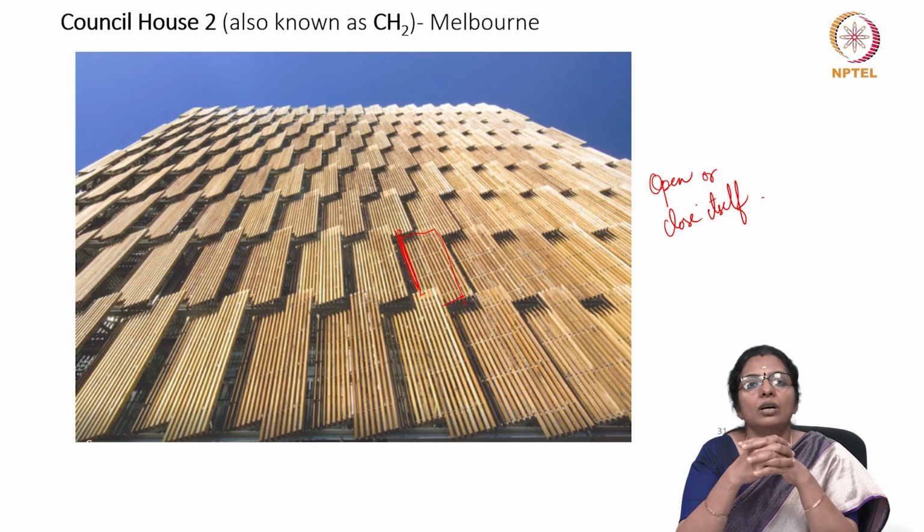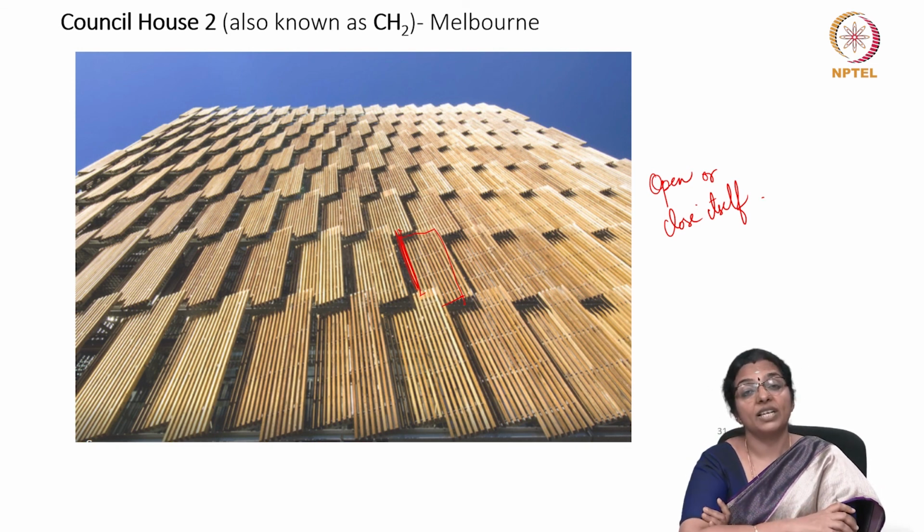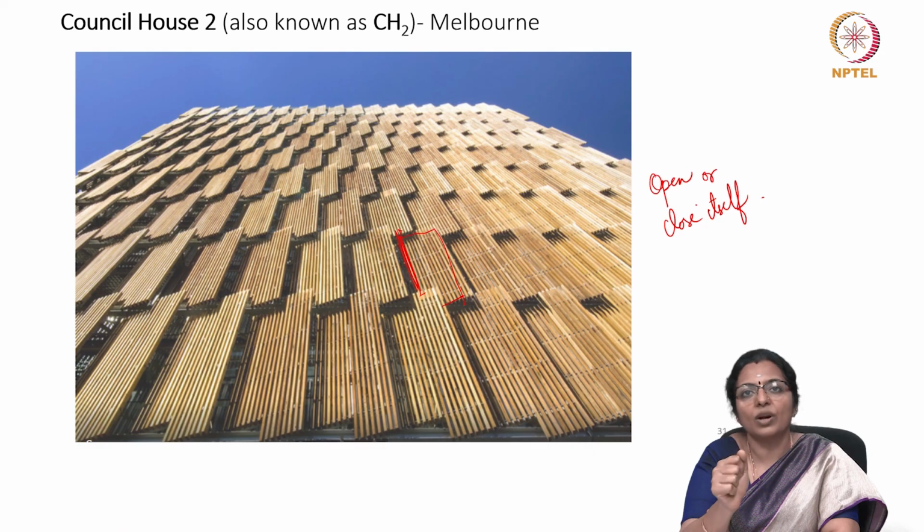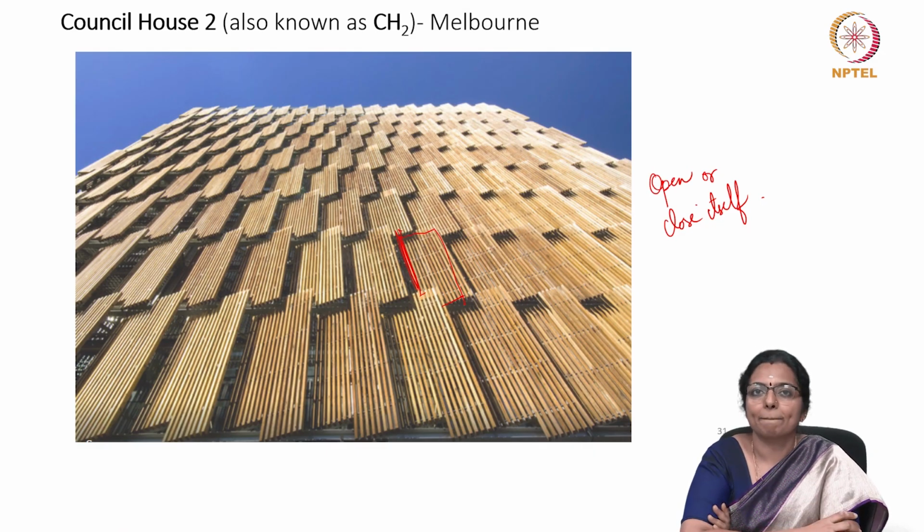And therefore, kinetic facades, even though their initial embodied energy may be slightly higher, will definitely in the long run be productive by having a reduced operational energy throughout the lifespan of the building, in addition to empowering the user with whatever is needed. The user is empowered to control it in terms of daylighting, solar radiation, and probably wind.